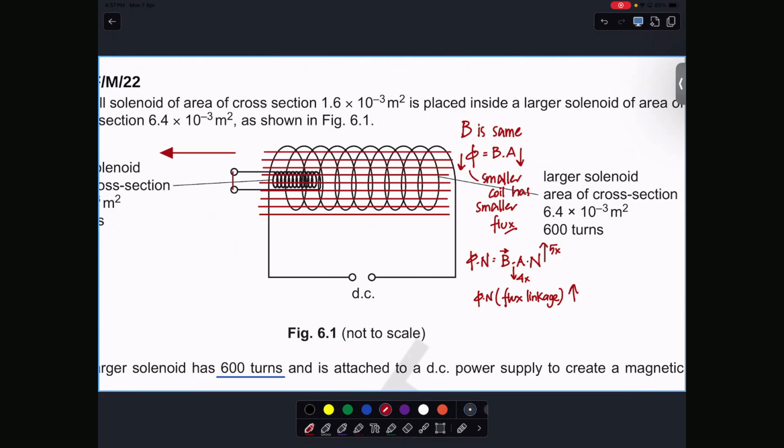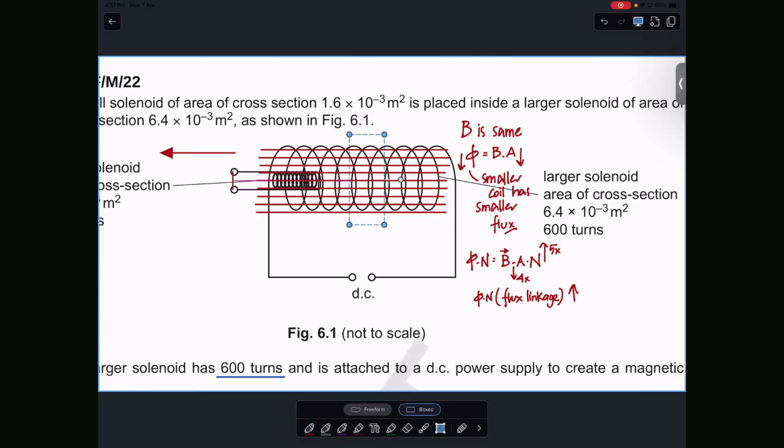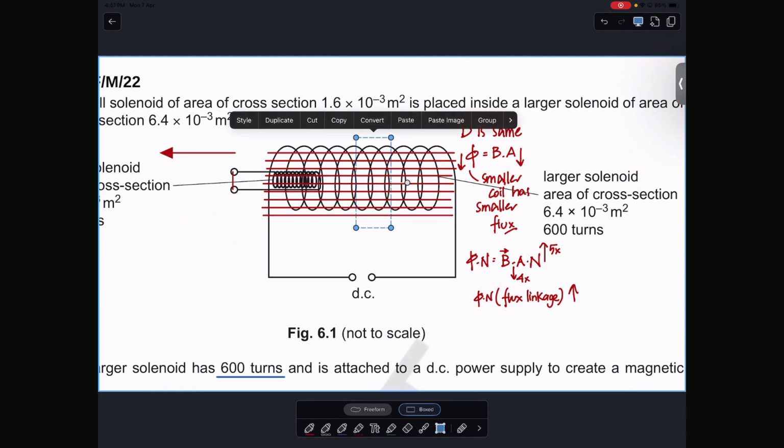They produce an opposing force, an attractive force. Let me explain what is happening: as you try to move this thing, what does the smaller coil do? The smaller coil cuts the magnetic field lines here, and in the smaller coil, what is induced? EMF. But it's a connected coil, which means what will be able to flow through it? Current. And whenever there's current flowing through a solenoid or a coil, what is produced around it?